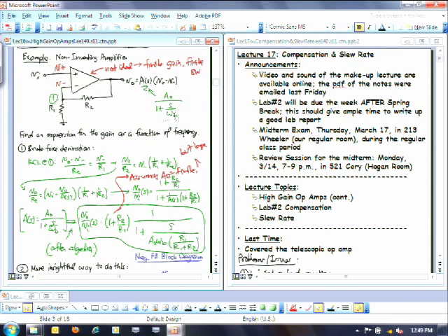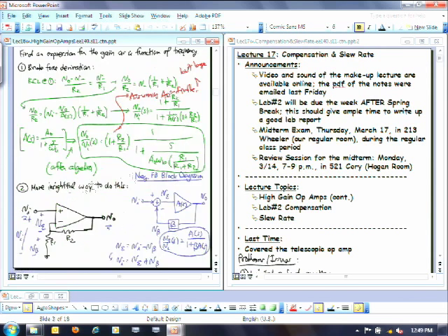We then went through looking at this from almost an inspection-like technique, where we equated this circuit to that classic feedback system block diagram that you all know very well. So this now becomes a matter of identifying what beta is. What part of this circuit creates beta? Just looking at these circuits, we were able to say that R1 and R2 created beta.